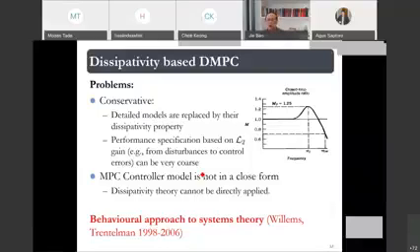But we all know that if you've got a dynamical system and you look at the gain or the frequency response, you would have a peak somewhere at a certain frequency, and the L2 gain represents the largest possible gain. So if you think about the sensitivity function from disturbance to process output, we want the gain to be very small, but at certain frequencies it will be very large.